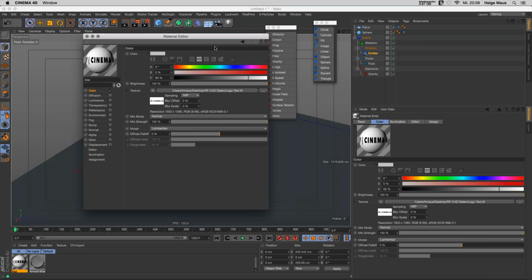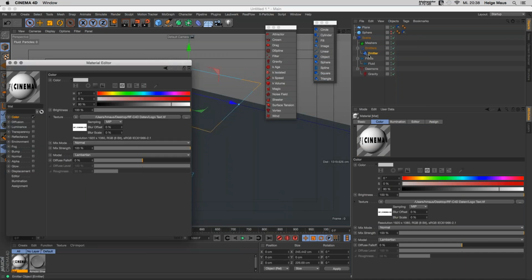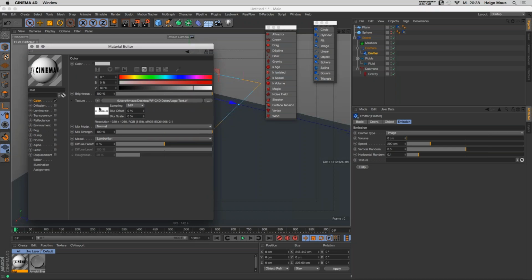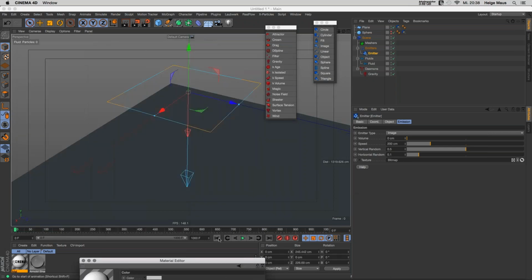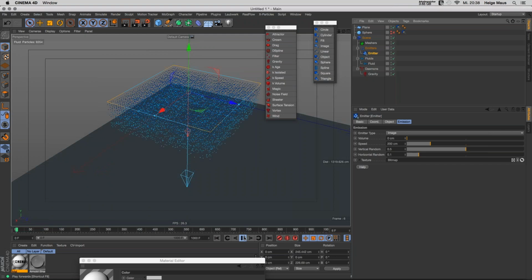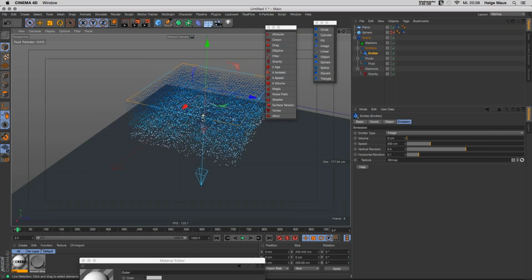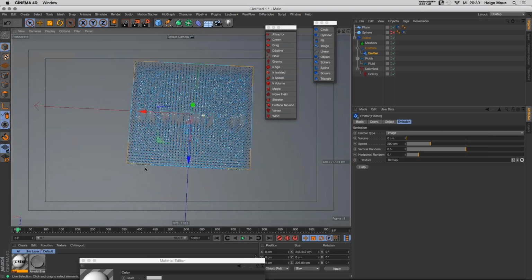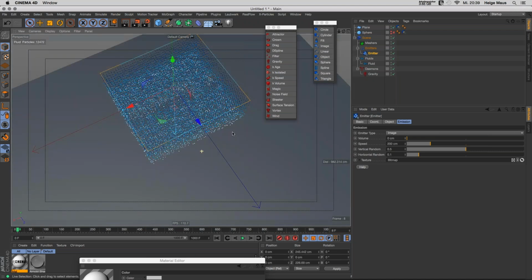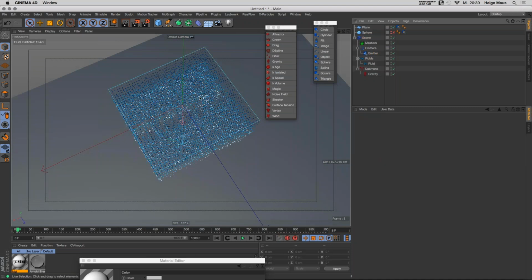And I take this texture now, and to assign this texture now to this image emitter, you have to stay in your material editor, take the texture itself and drag it over so that you get a connection to this. And if you now press play here, you see, okay, sphere is still on. I deactivate this. For a moment, you see now that we get all the rest. I can make it clearer.